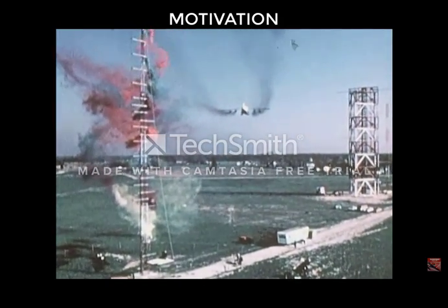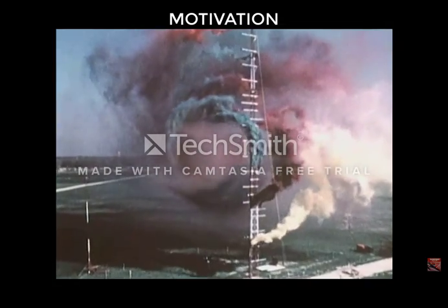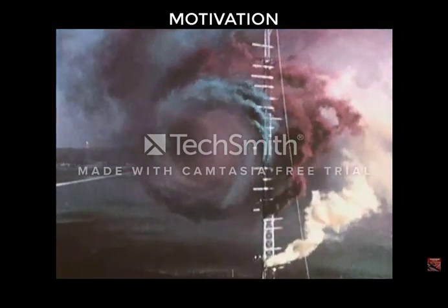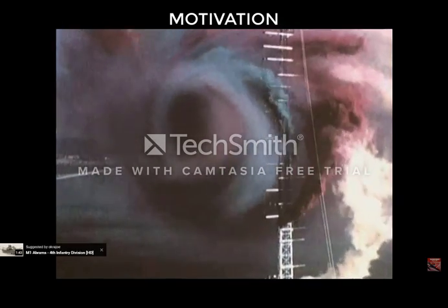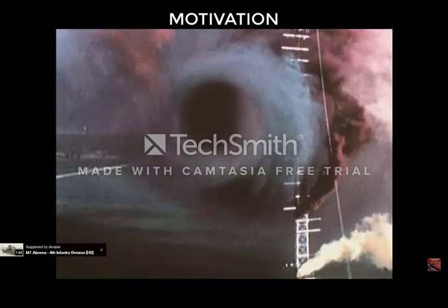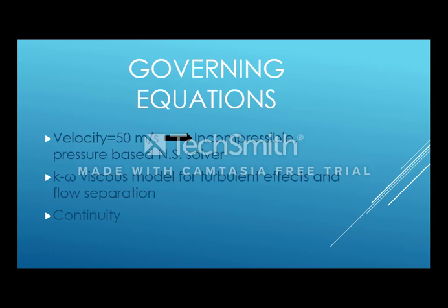I did this by solving the flow around the same airfoil with and without a winglet and at 4 different angles of attack. The setup of my problem was representative of an aircraft taking off, which is one scenario in which the vortices can be the strongest and have the largest impact on aircraft. Since the wing was modeled through flow similar to that found during takeoff, a relatively low velocity of 50 meters per second was used. This allowed an incompressible, pressure-based solver to be used to solve the Navier-Stokes equations.